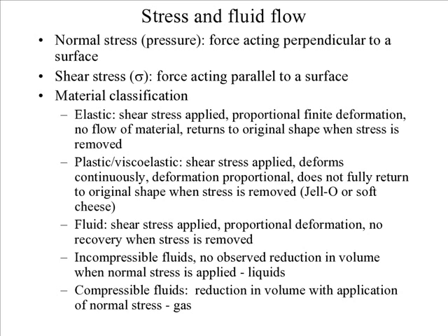When you have a fluid, when shear stress is applied, you have proportional deformation, and there's no recovery when the stress is removed. Materials classified as incompressible fluids show no observed reduction in volume when normal stress is applied, and normally those are liquids. Compressible fluids show a reduction in volume with application of normal stress, which is a gas.